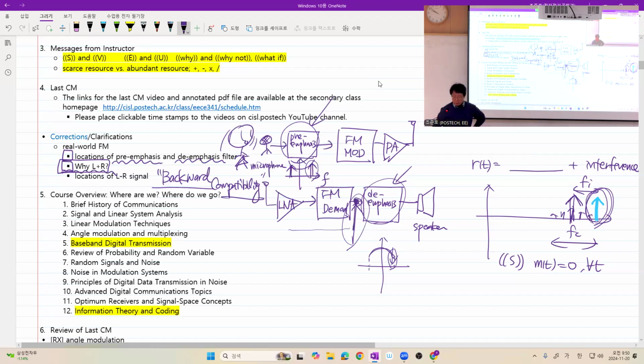So the right side signal and left side signal are combined, and then we have a difference, so that in order to recover the right side signal, we subtract, and in order to recover the left side signal, we add up these two, something like that. Got it? Okay. And also, in the figure,